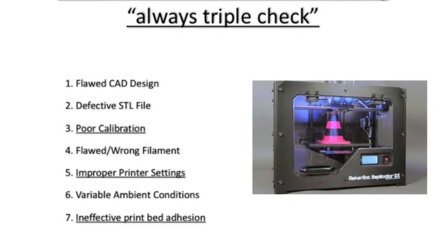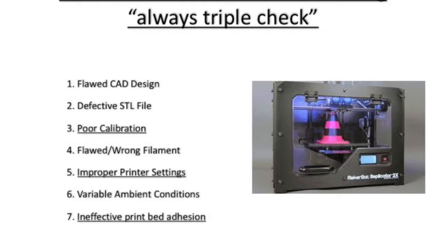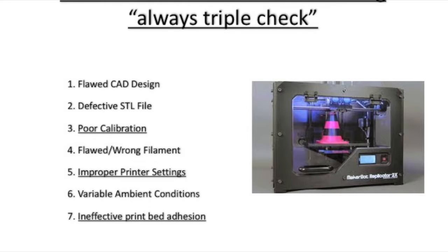In addition to the poor bed plate adhesion, there are also issues that can occur with the extruder nozzles. So the other option is to make sure that the heating is going properly and that your calibration lines are actually extruding properly. Typically, if there is a clog in the extruder, you will be asked to contact one of the lead trainers on the tool to make sure that they can unclog the extruder nozzle. It does happen, and it ideally happens when there is not enough plastic or the temperature is not appropriate for the plastic or the filament that you are using to do your 3D print.